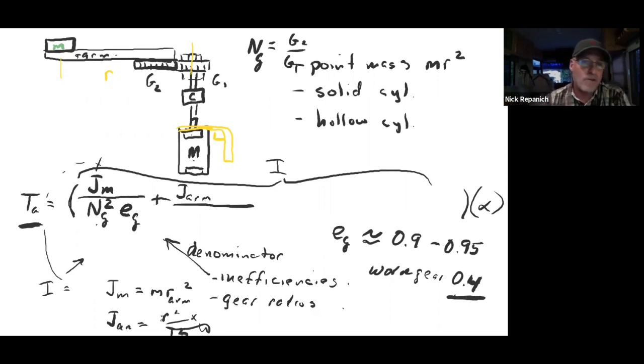But for now, this is really an estimation anyway, because do any of these components actually exist other than in SolidWorks? No. Sometimes you get a machine where you go out and you're retrofitting it and they're already there. But half the time when you're doing that, you don't want to use those components anyway because they did not minimize that term. They just made it work. And all of a sudden now you're doing motion control. You are trying to minimize inertia and maximize stiffness.